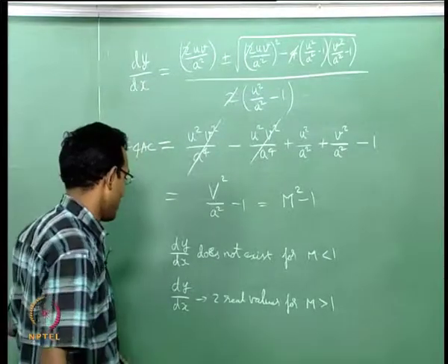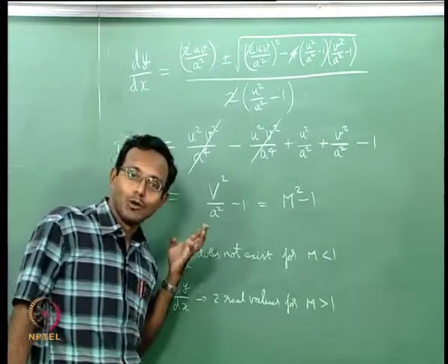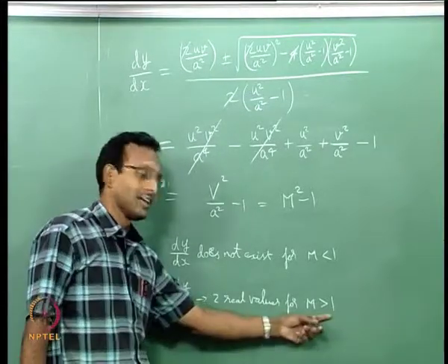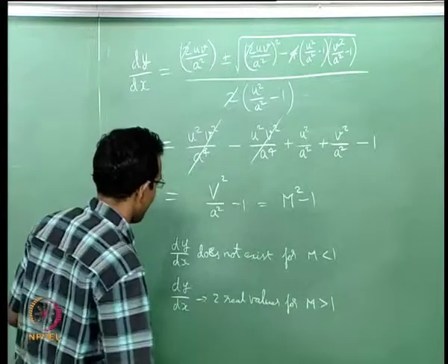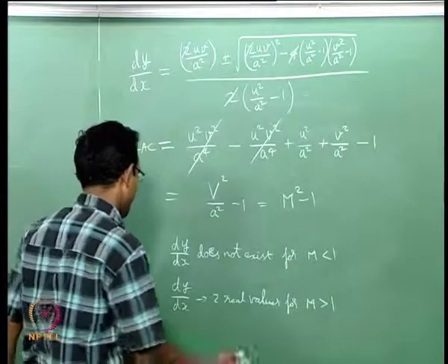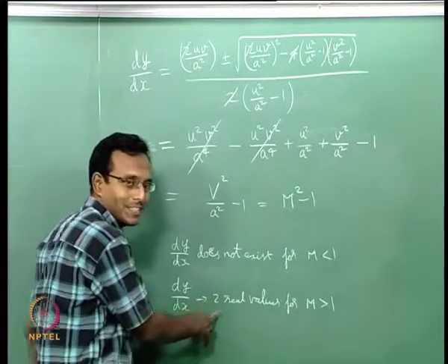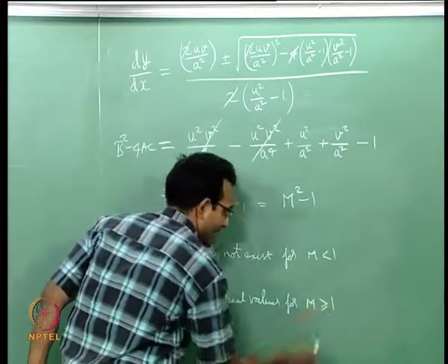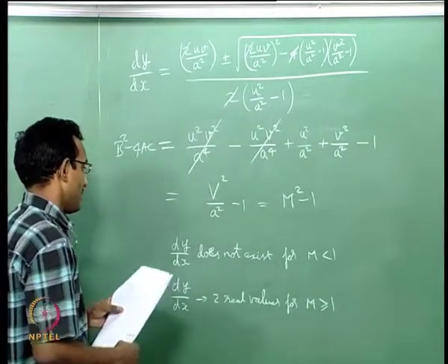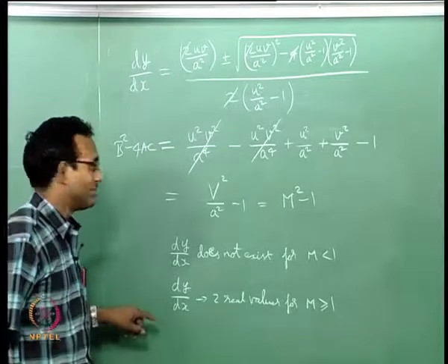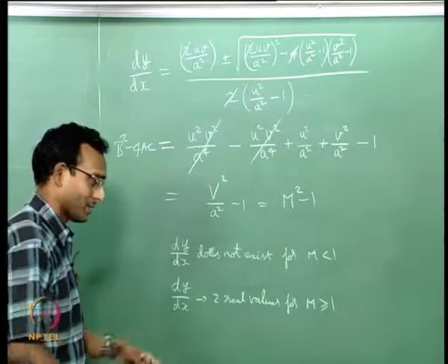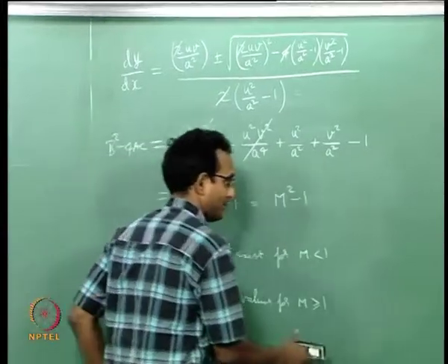I am going to say I want to solve for supersonic flow alone, no subsonic flow in my flow field, then I can go directly into this part. Then I will say yes, I have this particular condition. If M equal to 1 happens, then that is not really bad. It so happens that the two values will be the same value. So I might as well add this to be M greater than or equal to 1 in here. Okay. We still haven't found the value for dy by dx. We did only halfway. We have just done what is inside the square root. We have to do the remaining terms. We will do the remaining also now.